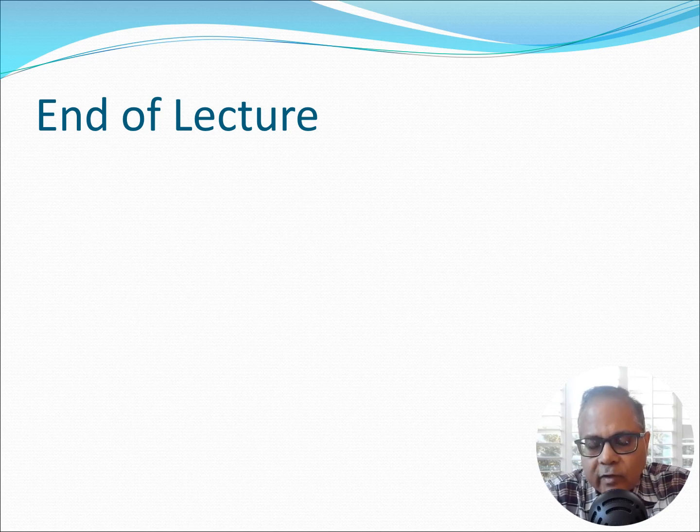We started moving from steady level flight to climbing flight, and next we are going to discuss some important concepts, specifically service ceiling and absolute ceiling, because there is a point beyond which the aircraft cannot fly. As you have probably understood from some of these graphs, it is related to the concept of excess power: there is going to be a certain point where excess power is simply not there, and that limits the height to which you are able to climb.